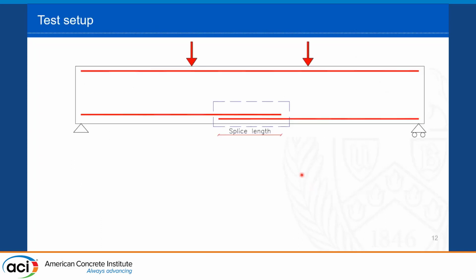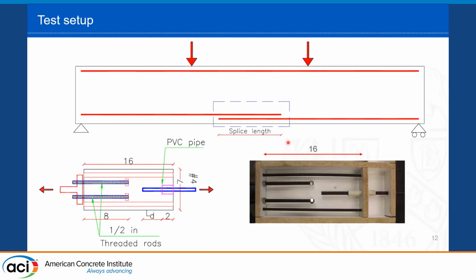When testing the bond, the most optimum test setup is a beam setup with the splice region at the uniform tensile stress of the steel rebar, until reaching yield. But beam tests are expensive and very time consuming, so it's not easy to do beam tests to study a large number of parameters. So instead of beam tests, I did a modified double pull-out test.